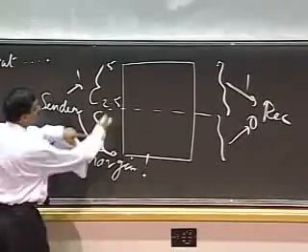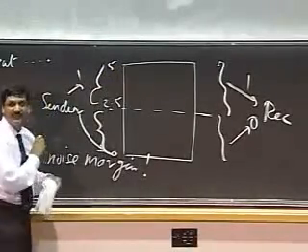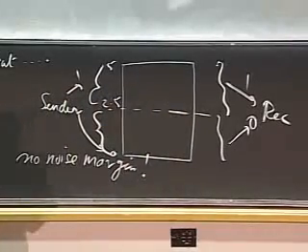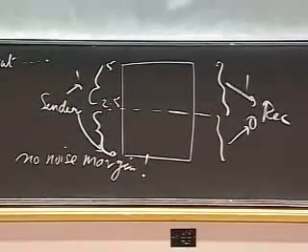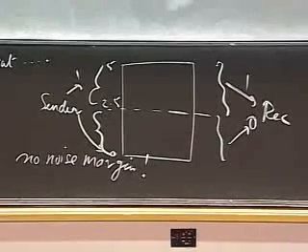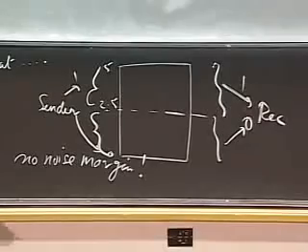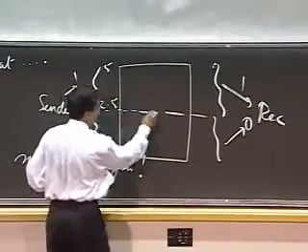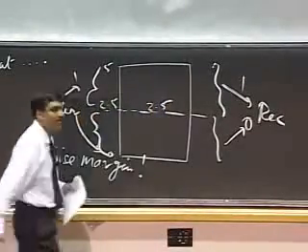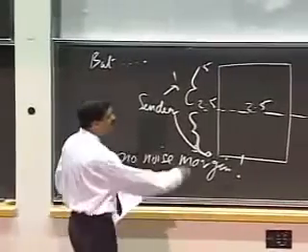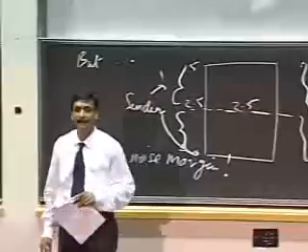Because if I allow the sender to send any value between 2.5 and 5, then what if I have a value of 2.5 for a 1, and then I may end up getting very little noise margin on the other side. Worse yet, what if I get a value 2.5? That's a much worse situation. What if the receiver receives a value of 2.5?